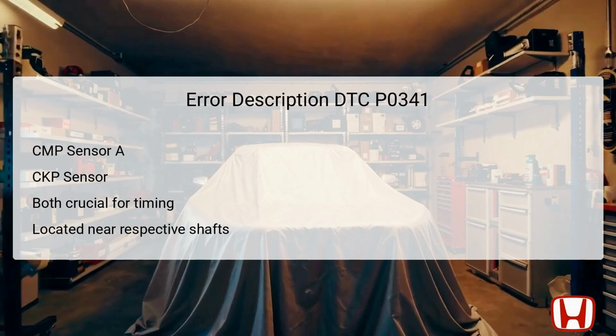The CMP sensor, which monitors the position of the camshaft, plays a vital role in ensuring the engine's timing is precise. Located on the camshaft, this sensor sends signals to the Engine Control Module, ECM, to help regulate fuel injection and ignition timing. The CKP sensor, on the other hand, tracks the position of the crankshaft, vital for monitoring engine speed and rotation. This sensor is typically mounted on the crankshaft or near it, capturing its rotational speed and position to synchronize with the CMP sensor's data.